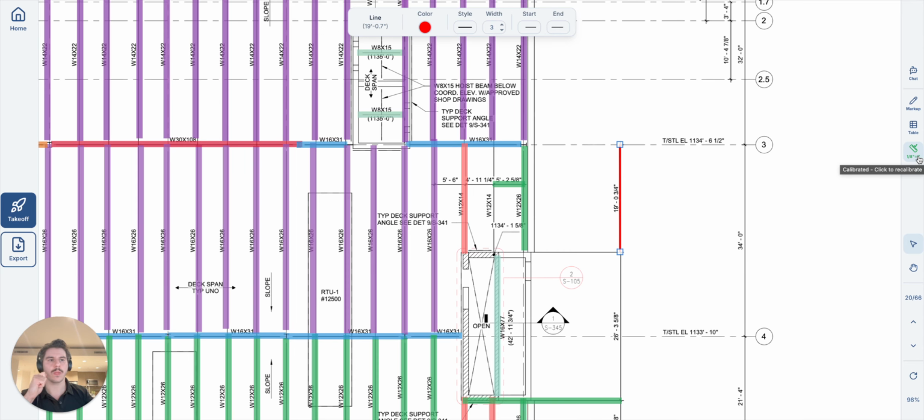Easy. Now I want to comment briefly on why this is so important, because I really want to drive home that you folks got to check this with every page you do in our platform, or anytime you do a takeoff anywhere really. As you folks all know, material costs are taken by weight. And weight is calculated by inches on the paper times your conversion to real life feet, that's what we just looked at, the 1/8 to 1, times your pounds per foot. So if you do the measurement, you can check that pretty readily.